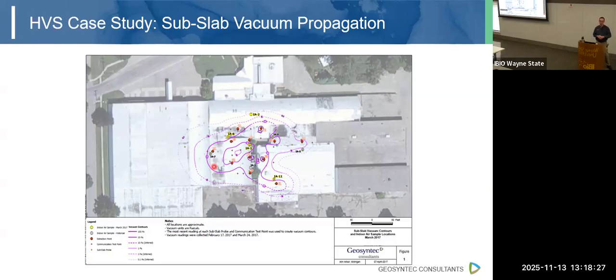For the mitigation system itself, the vapors that we're capturing should be going up above the building and then mixing and diluting with the outdoor air. And there's guidance about where that extraction point, that discharge point, needs to be, so that you're giving it enough room to mix with the outdoor air and not having those vapors go up and then get sucked into somebody's window. So it needs to be above the roof line, a certain distance away from other buildings, and a certain distance away from doors, windows, and entry points for heating and cooling systems.